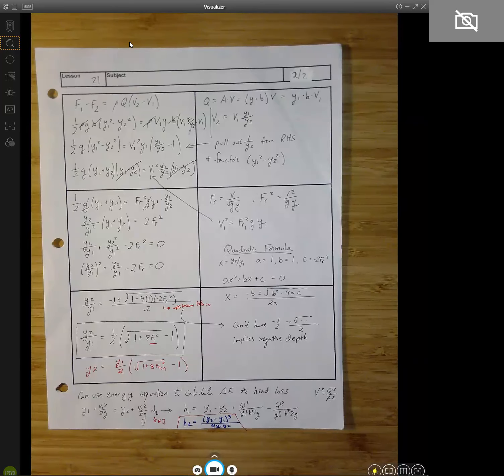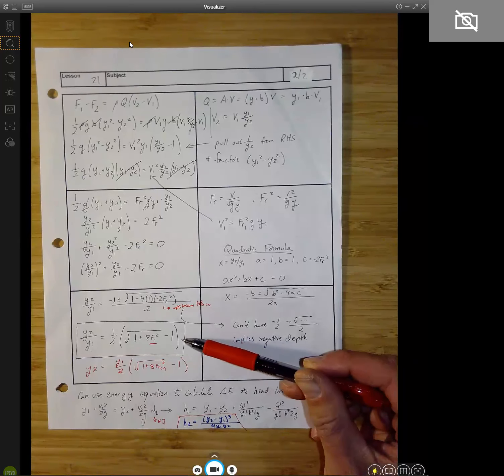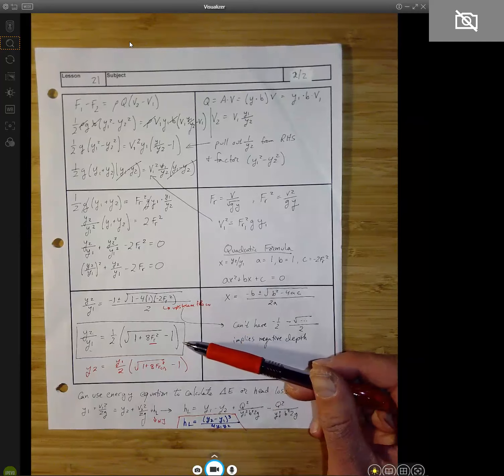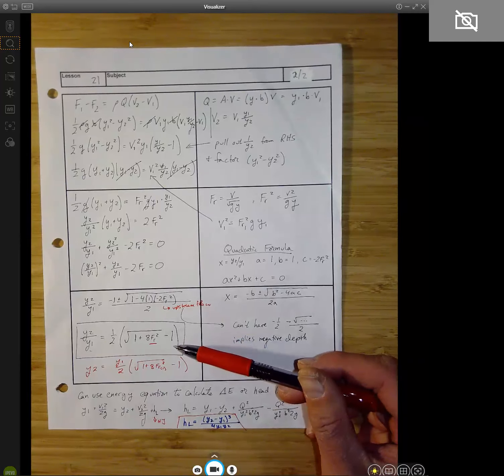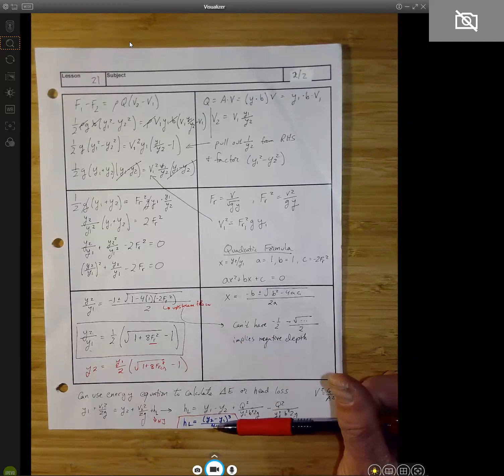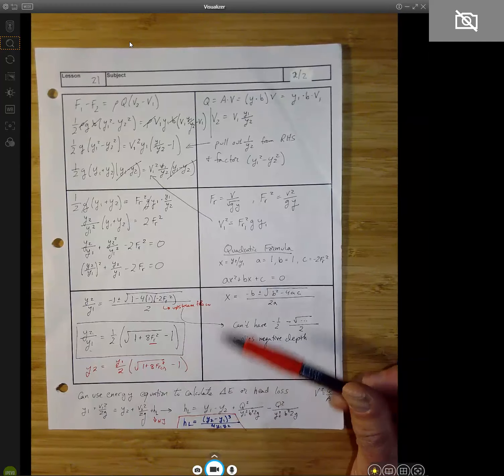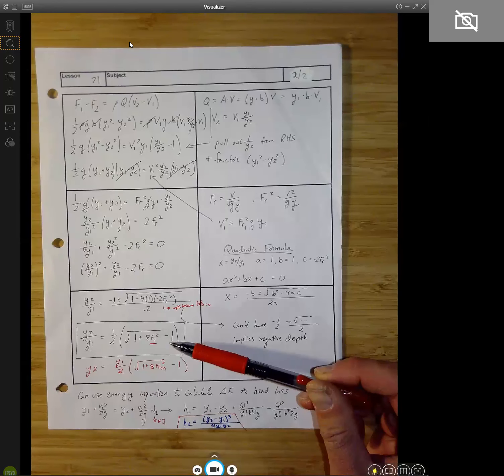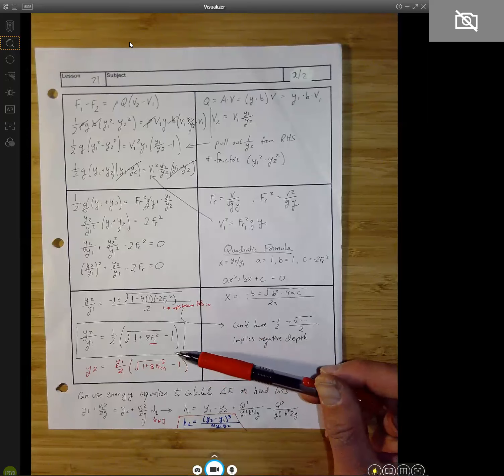So this is a classic FE problem. That's why we're making sure we cover it here. There's obviously more nuance and things that happen with hydraulic jumps, and we can actually figure out how to design energy dissipators downstream of spillways to result in a certain amount of head loss from the hydraulic jump, as well as control what that downstream flow depth is going to be, which could have important consequences for infrastructure.